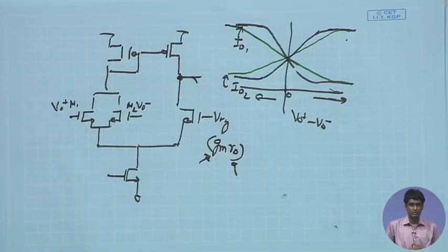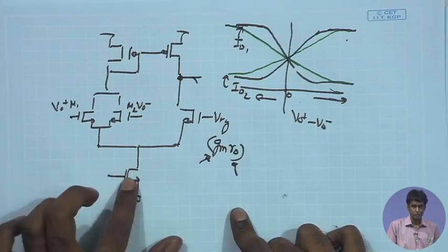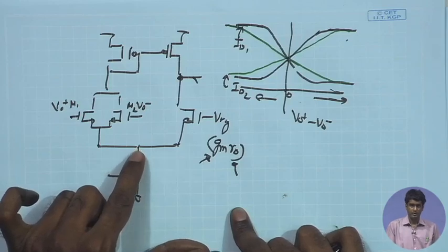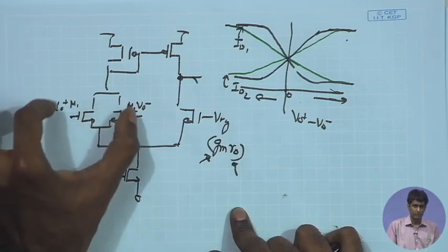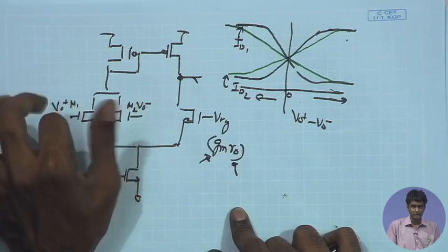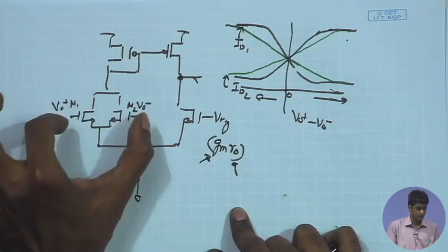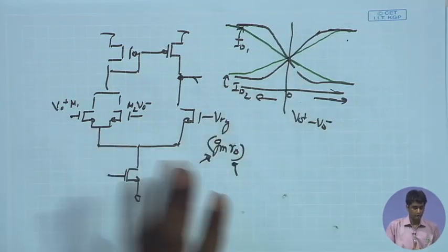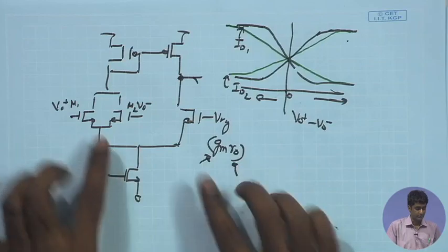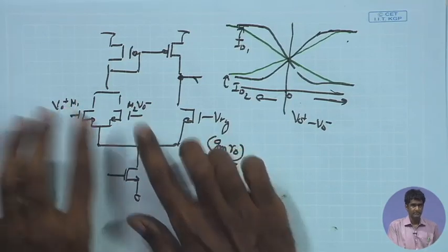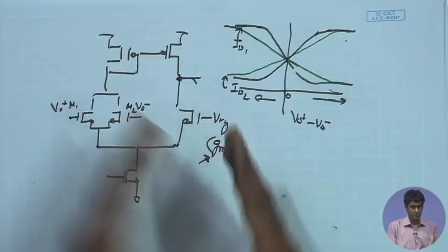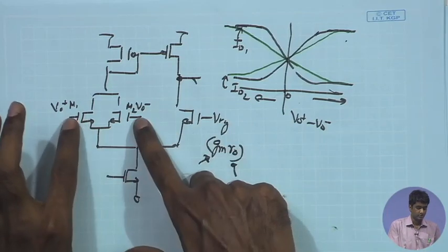And also another point will be to size this tail current source. If you make the tail current source sufficiently large, it will be able to handle a lower input signal over here, and that also increases the maximum swing, the differential swing that the common mode device can handle. That is another way, and we can have other alternatives also in cases where the output signal swing is sufficiently large and extraction of common mode using this scheme is failing. We can go for other schemes where you can handle larger output signal and where it is not constrained by such a differential swing.